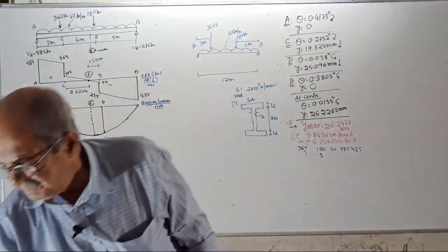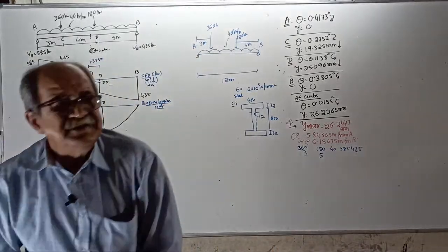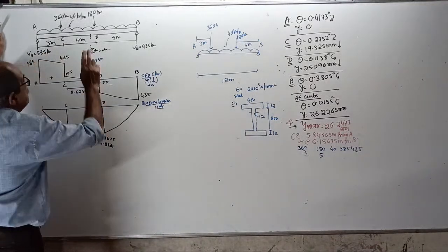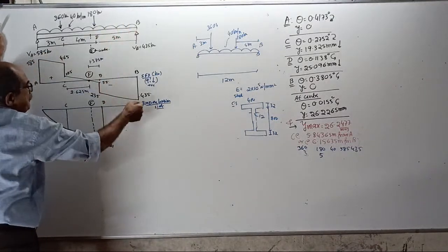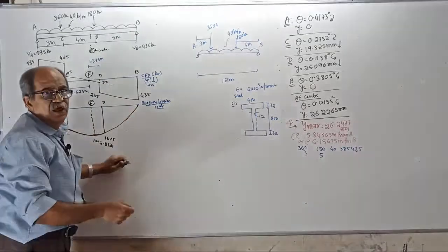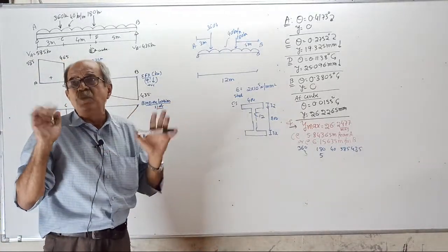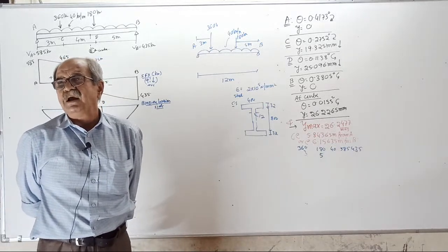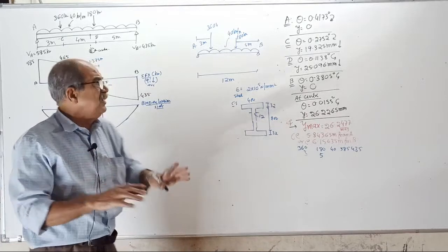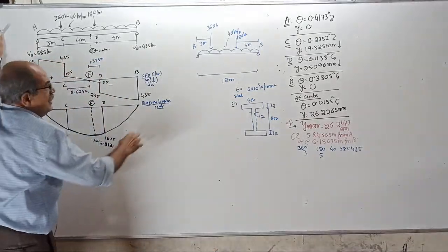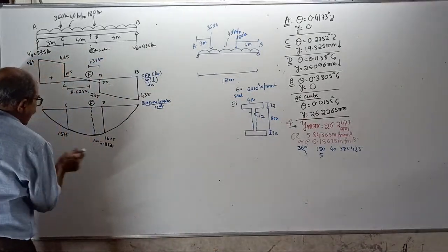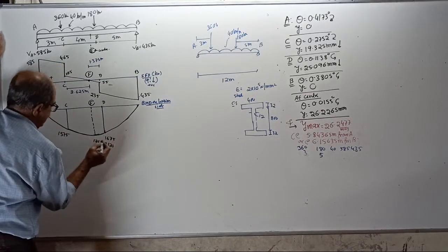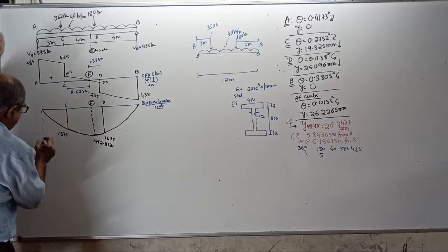Okay. Now, draw the elastic curve. Remember, this parabola turns this way sometimes. If there is no load, BMD will be straight. Remember, all those things, linear variation and parabolic variation, are for the bending moment diagram. But remember, the elastic curve is always a curvature. You will never get a straight line. So now below 1765, I will project and put the elastic curve.